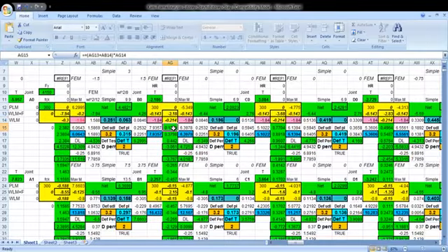Now how we calculate? You see, we say AG13. Now AG13 is same value here. We add to this AB14, and this is AB14 here. Because there is only one opposite, we cannot take this for column, so we are taking AG13 plus AB14 into AG14. This is the factor multiplied by rotation of the factor, so we get this value. Now we have to go here, because there are three members, so this value we have to work out.